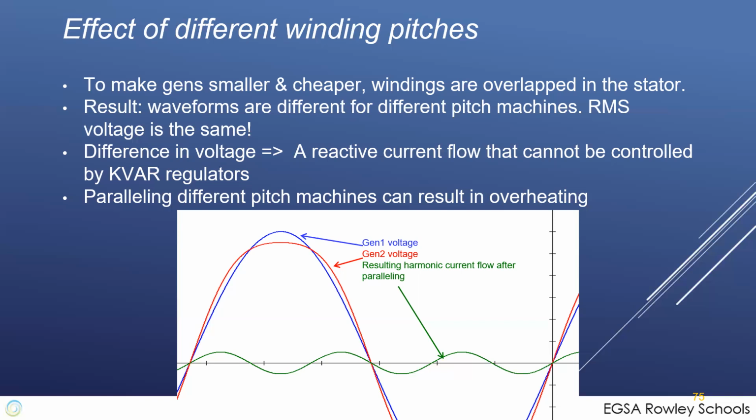All the windings under the pole face, the rotor pole face at that time, are all the same phase. Well, they started laying the other phases under the pole face at the same time in order to make the machine smaller. They found they could make the machine smaller, lighter, cheaper. But what happens is they sacrifice a little bit the waveform. So here, they've overlapped the windings in from B and C onto the A windings.